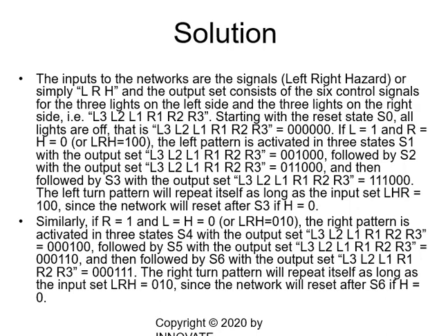The left turn will repeat itself as the input set LRH will be 100, and if H continues to be 0, the cycle will repeat itself because we will go to the reset state as long as the left request is still 1, so we continue with the cycle over and over again by activating 1 light, then 2 lights, then 3 left lights. Similarly, when we request right turn.